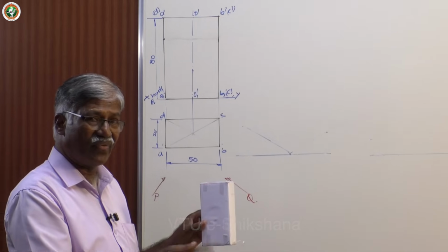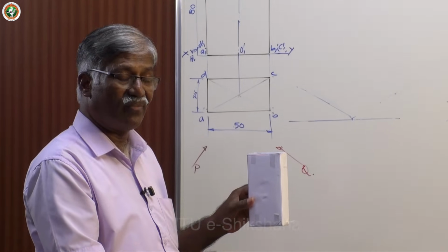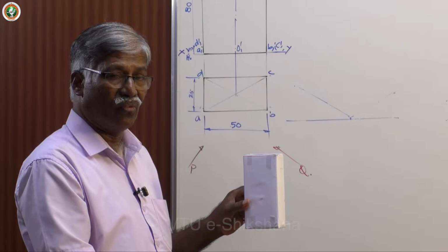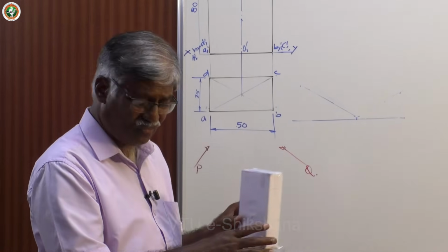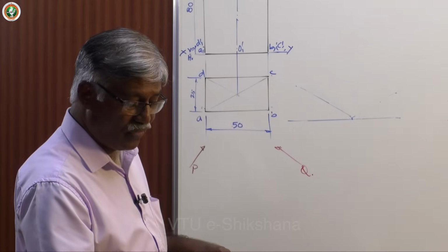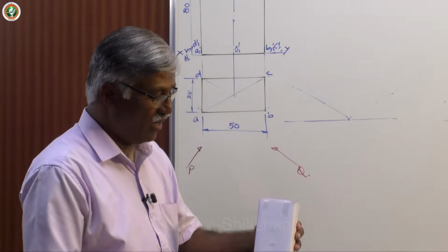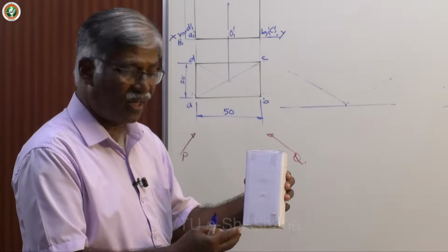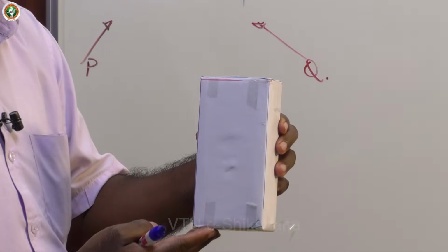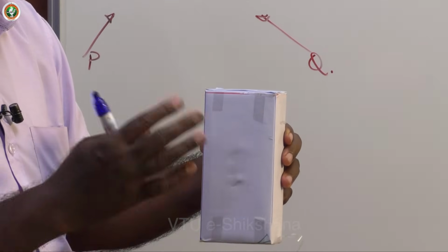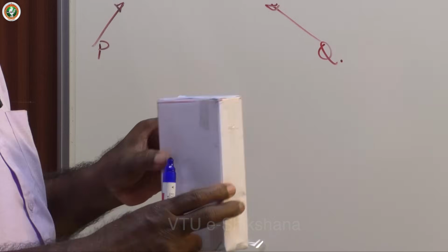I will tell you the difference between view, drawing and projection later. For right now, let us consider view. Now let me draw the isometric view for this. If you take up this particular figure, all base edges are parallel to HP or on HP, and all longer edges are perpendicular to HP. Now let me draw the isometric view.